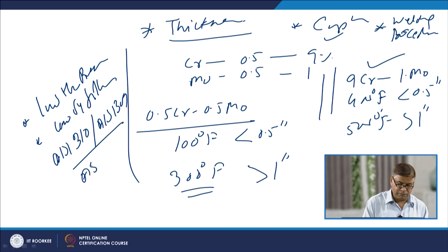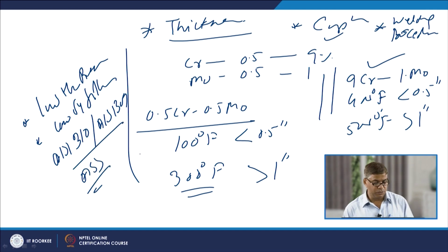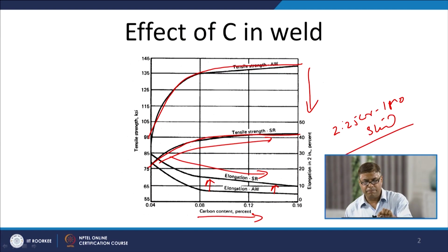These are the austenitic fillers which will have the greater absorption of the hydrogen, as well as these will be offering the lower yield strength. So, lower residual stresses will be developed, and these factors in combination will be favorable from the preheat point of view, because even the lower preheats will be suitable to develop the weld joint.